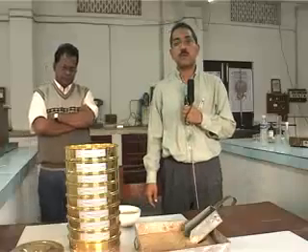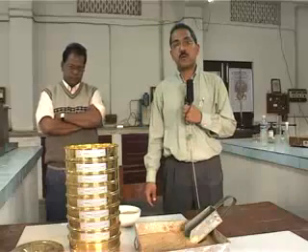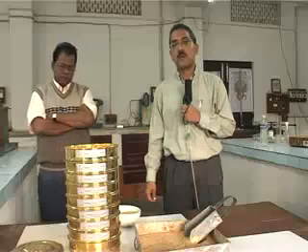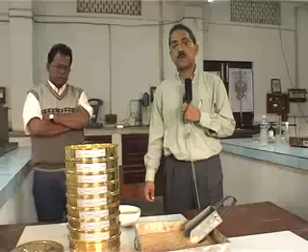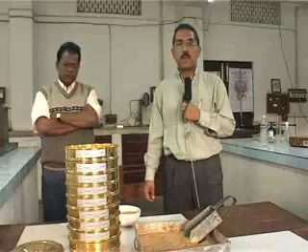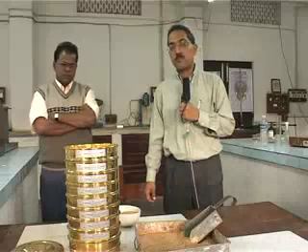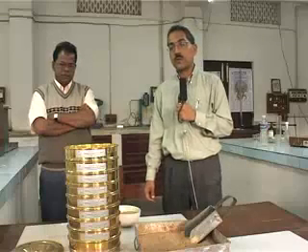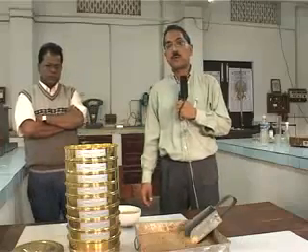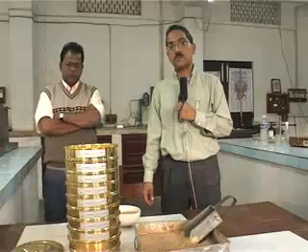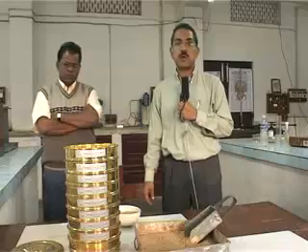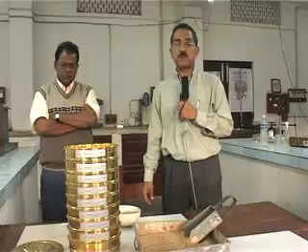Here we are going to give the demonstrations on different simple laboratory testing for classification and identification of key soil parameters and rock parameters. With that said, we are going to move on to the first laboratory experiment involving sieve analysis, which is carried out to find out the distribution of grain size, or representation of different grain sizes within the soil matrix, for coarse grained soils.